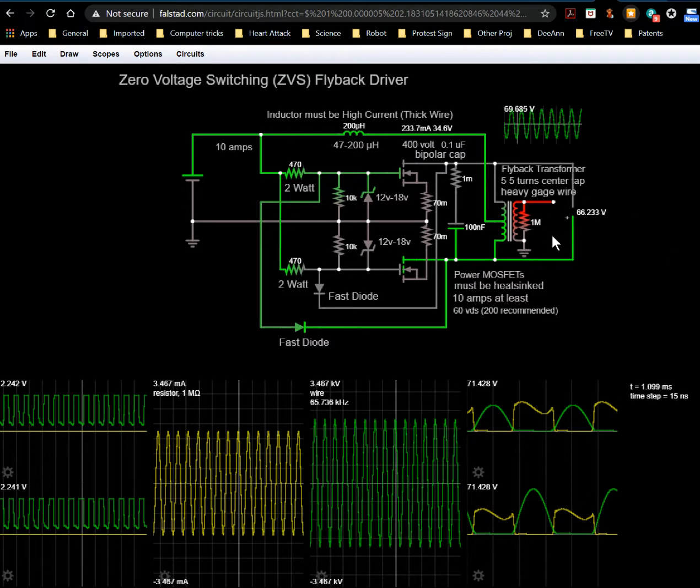It's definitely true that if you take an air coil, like for example in an induction heater with no load on it, nothing inside the coil, and stick that on an LC meter, its inductance will change depending on whether you've got something metallic or not.